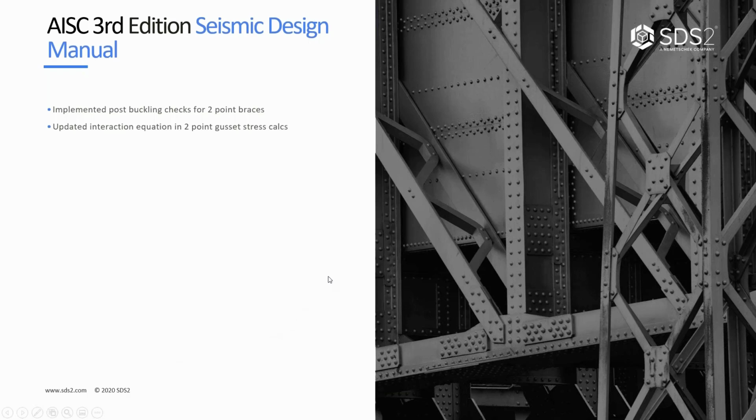And you'll also see we've updated the interaction formulas that we use in the gusset stress calcs. We used to have just a linear interaction formula, and we now use the formula that's shown in the design examples in the seismic manual. You can also find that formula in part 9 of the regular steel manual. That's the extent of the braced frame updates that we had to make.